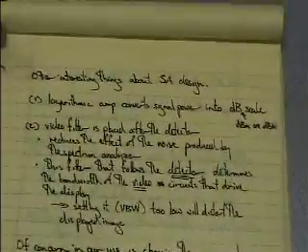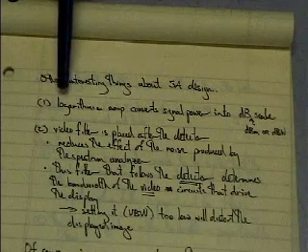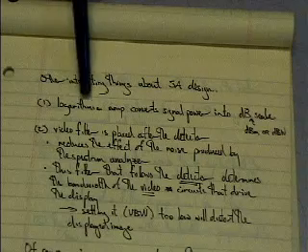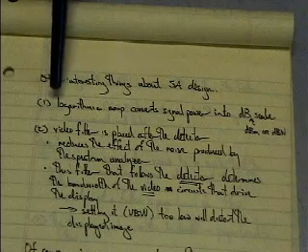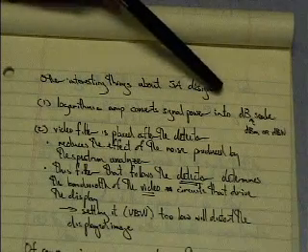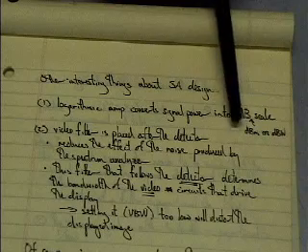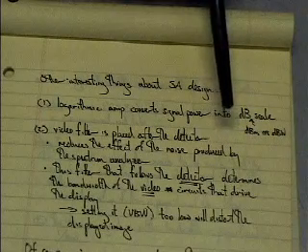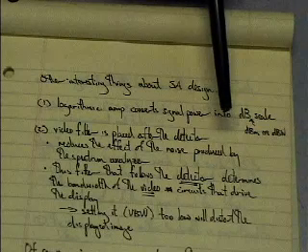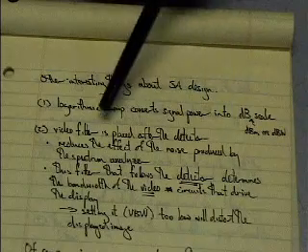Okay. So a couple other things that are interesting in spectrum analyzer design is that the amplifier at the output of the power detector is a logarithmic amplifier. So it automatically converts the display into the dB scale. That is, you're going to be looking at dBm. There's no mathematical conversion being done in the spectrum analyzer. It's actually done with an amplifier that has a logarithmic input-output curve characteristic.